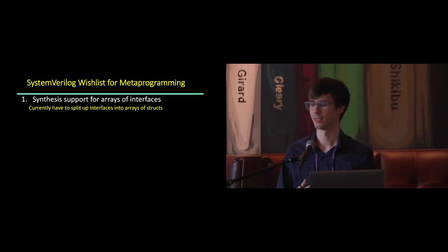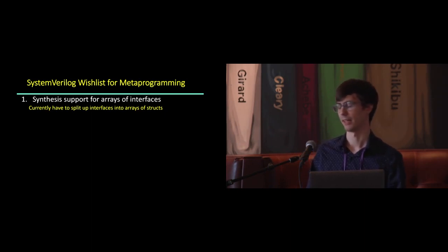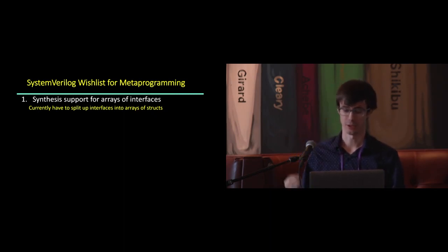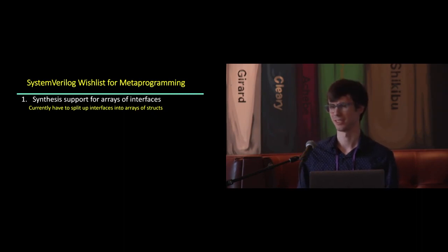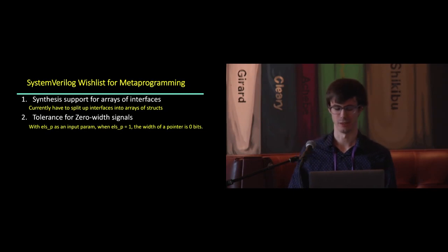which have these nice ready-valid properties, parameterizable widths. But then once you get into the synthesis level, it actually splits them automatically, and now your backend scripts have broken because names have changed. So we stick with hard-coded arrays of structs, which leads to parameterization being kind of difficult to do in SystemVerilog.